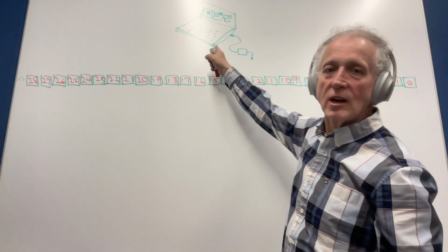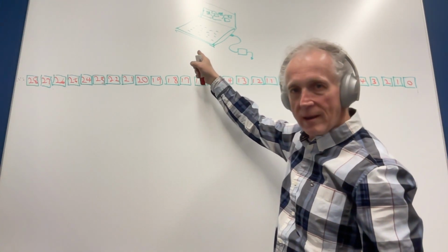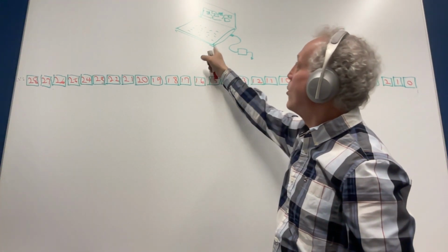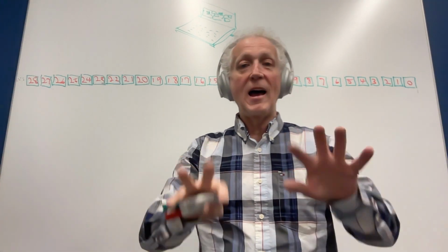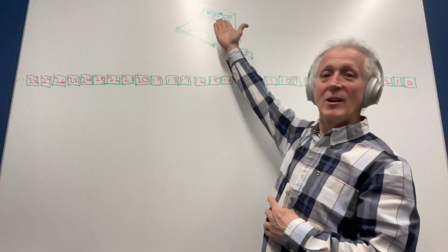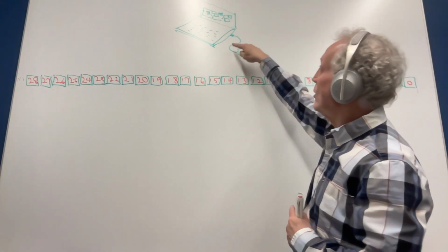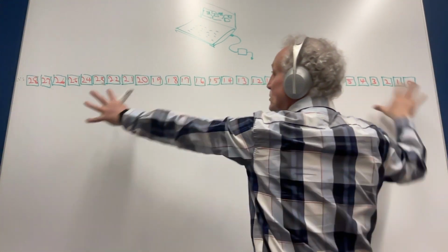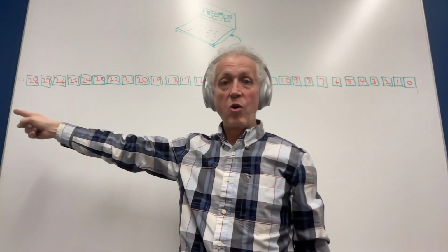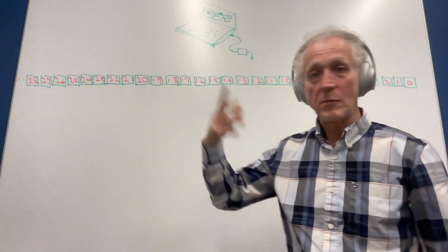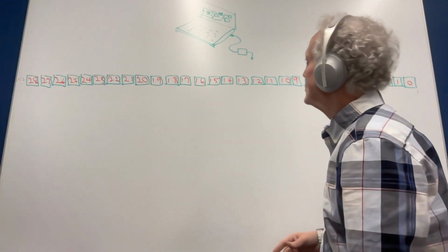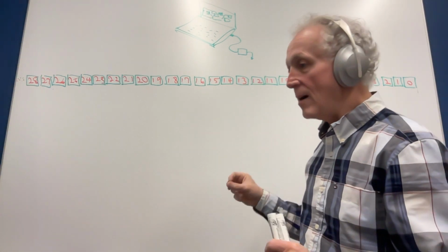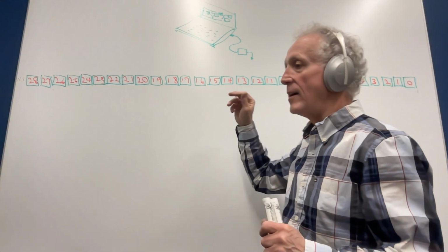And up here, and I apologize for the reflection and the lighting in here, is my poor representation of a laptop running Sigma Studio. And I have a little USB cable. There's a USB-I interface, and that comes into the eval board, the actual DSP that has the core, the 32-bit number in the core that the program is running in. So when you click readback, at that moment it'll go and get the core.